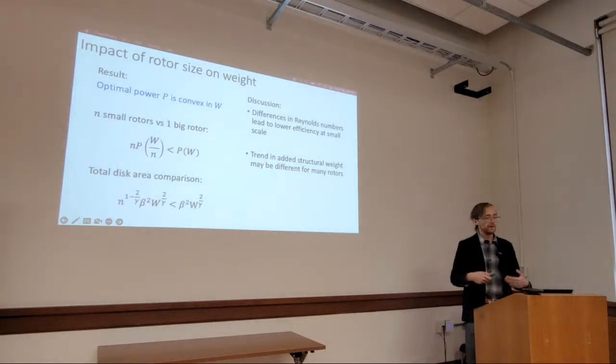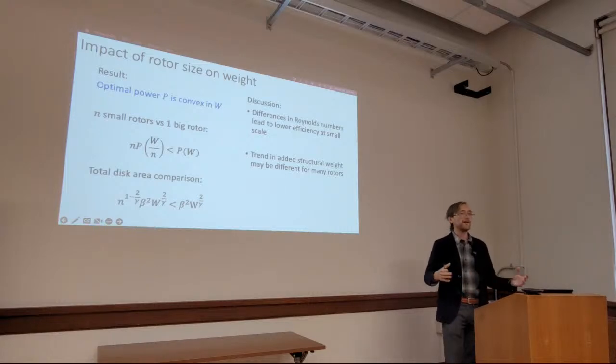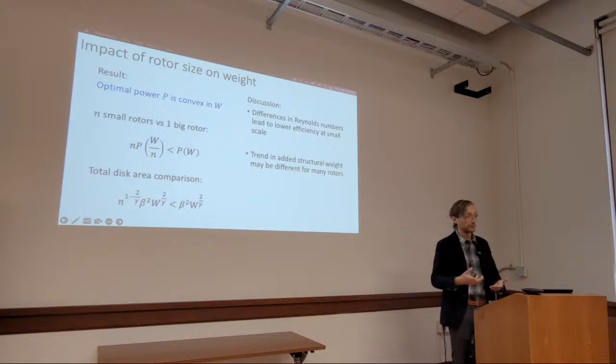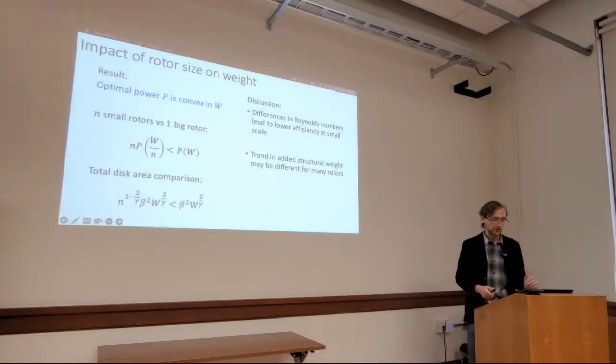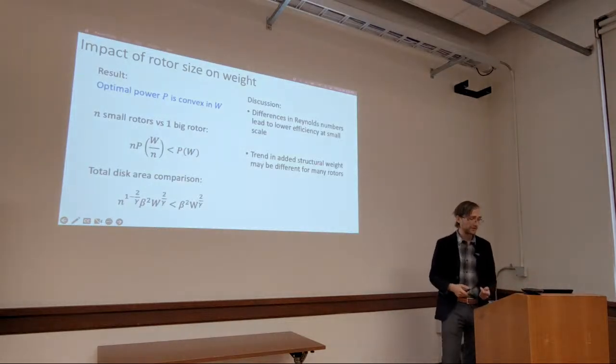And in general, there are many other factors to take into account. For example, maybe using smaller rotors means that more weight is actually required compared to just one rotor, in terms of the weight dependency on the size of the rotor, because we have to assemble these multiple rotors together. So there are some possible elements that make us think that maybe it's not always true. However, it could be that there are some cases where more rotors are better than one rotor, and I will come back to it and give you some practical examples of where that could be the case.